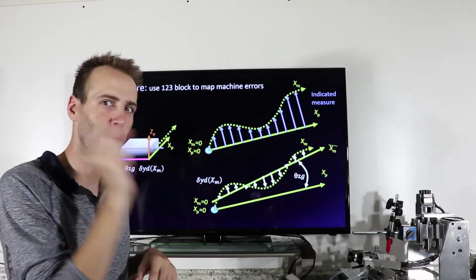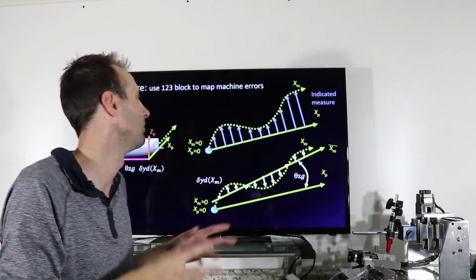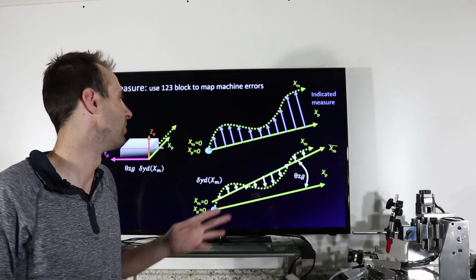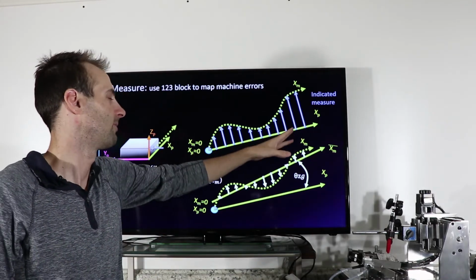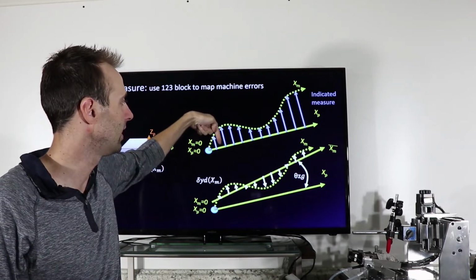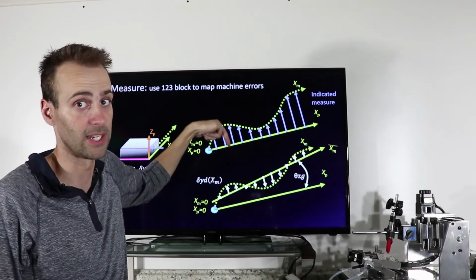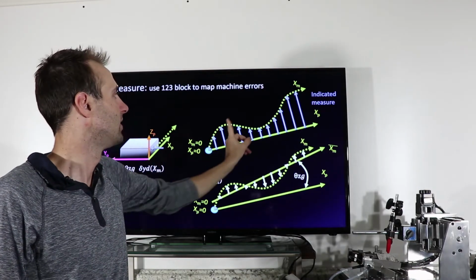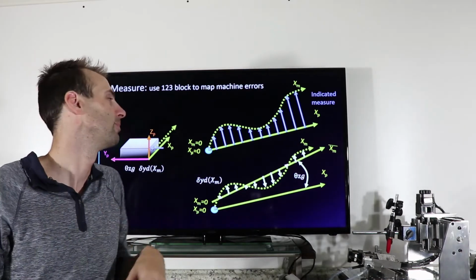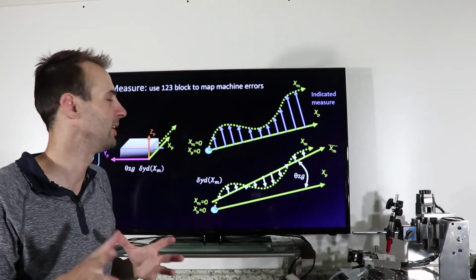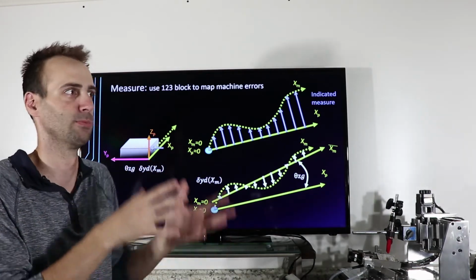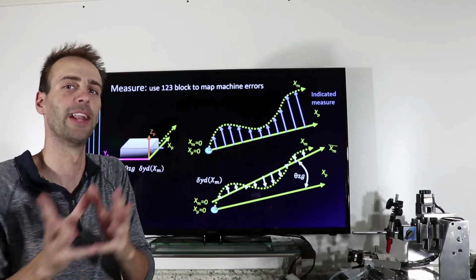You don't need to move one step on the stepper motor and take a measurement, because you just really care about that low frequency ripple, okay? So for example, I'm going to divide this motion into 10, and notice that these lines are perpendicular to the x face, not to the x motion. So that introduces a little bit of a cosine error, but it's okay. It will be close enough as long as your machine is more right than it is wrong.